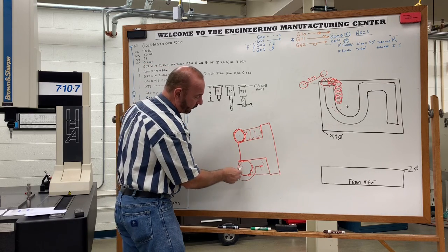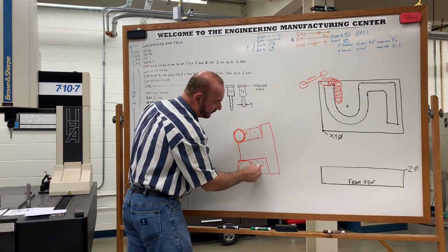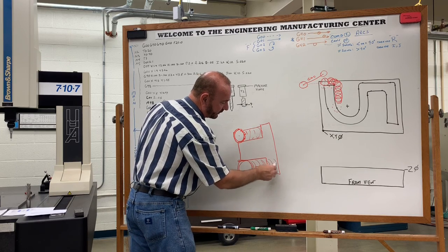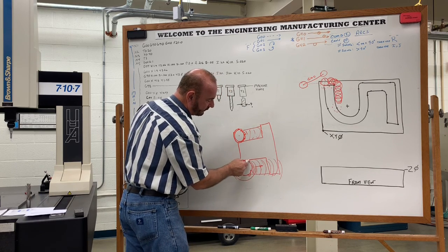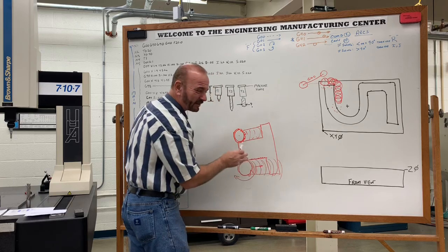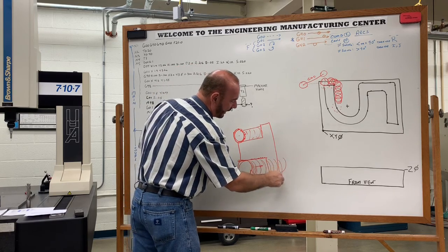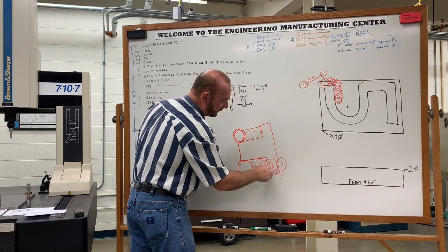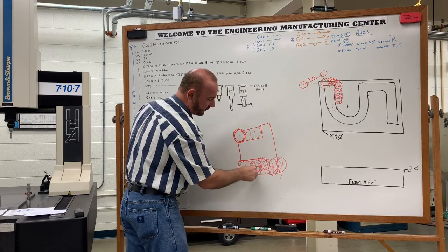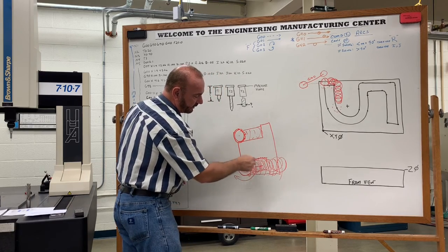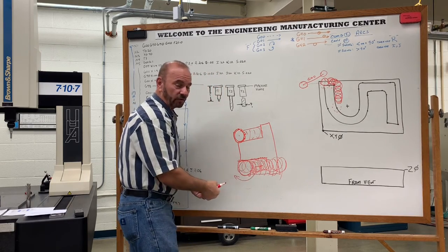So it's a safer way to cut larger pieces of material off, but of course that leaves kind of a not as good of a finish. So then we can come back with a lighter cut and climb cut it, and we won't have that situation happen because the cut is so light that you're in control of it.